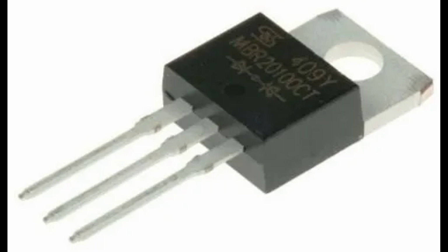Reduced signal distortion. Junction capacitance can cause signal distortion and reduce the accuracy of signals passing through the device. Minimizing capacitance helps preserve signal integrity. Lower power dissipation. In digital circuits, high junction capacitance can lead to increased power dissipation as the device charges and discharges the capacitance during switching. Lower capacitance reduces power losses.